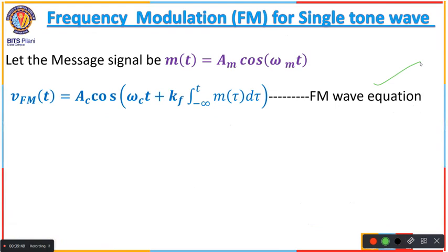Then how do you demodulate it? You converted amplitude to frequency, right? What do you do in demodulation? Reverse. Convert your frequency to amplitude and give it to the speaker. The same thing is happening in this system. You're converting your amplitude to frequency, and frequency to amplitude.